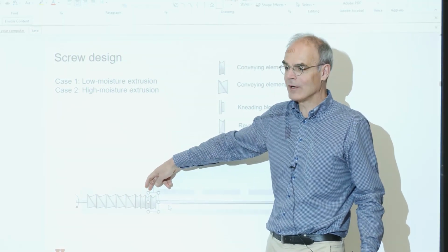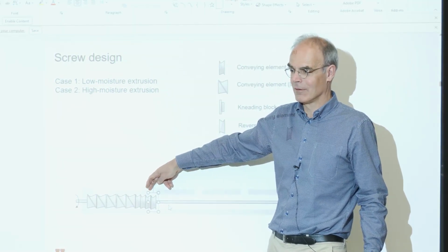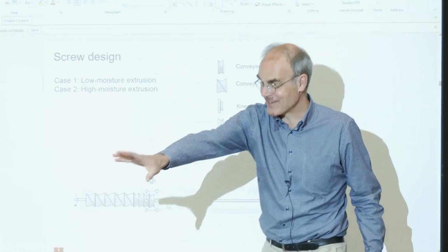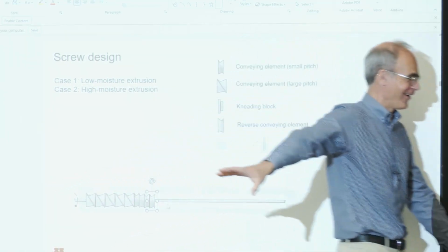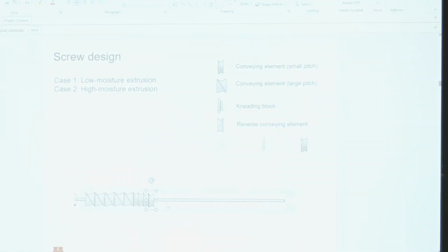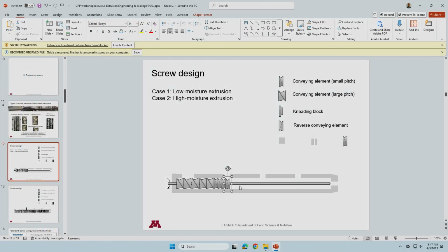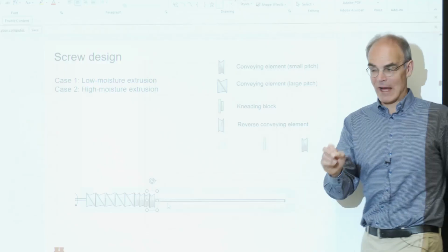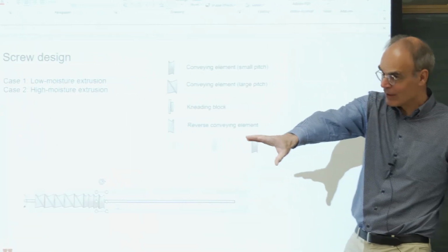First one. Why the first one? So that it can... Hydration. Exactly, you're on the hydration. I love that. That's really key. Because the temperature, so you start heating up, but you don't want to inject water where it's already way over 100 degrees centigrade. So here it's maybe 60 or 70 degrees centigrade, so we can easily have the water in. And we need to hydrate.